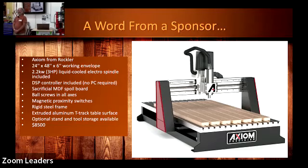And there's a tool database both in the design software and in the CAM software, the machine software, that offers recommendations on how fast it should turn, how fast you should feed in order to get the optimum cut. And similarly, a materials database about speeds for whether it be aluminum or brass or acrylic or wood. Correct. And those speeds and feeds, as Michael points out, are dependent upon the material you're cutting as well. Even hardwood, softwood, there's variations, right?